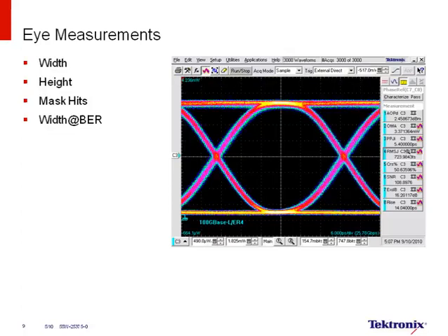For separate clock, forwarded clock, or discrete clock applications, you will use the clock to trigger the analysis and then view the data eye. For recovered clock applications, it is critical that you set up three things correctly. The first is you need to make sure that the loop bandwidth of the clock recovery is set up to the system you're looking at. Second, you need to set up the damping and peaking factor. And last of all, you need to set up the PLL order.